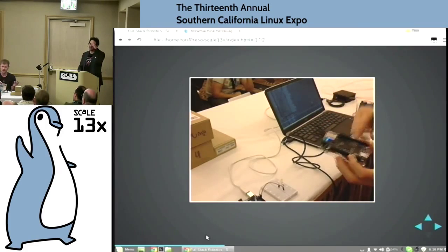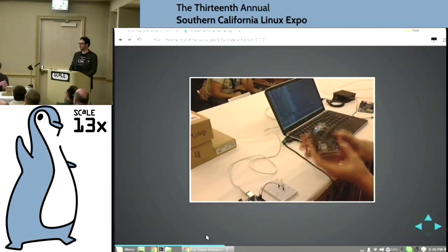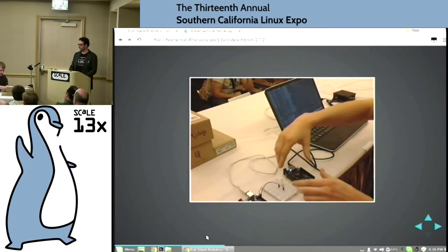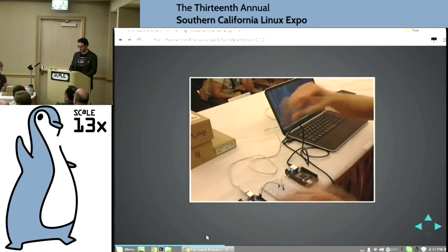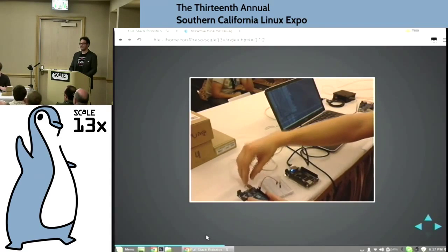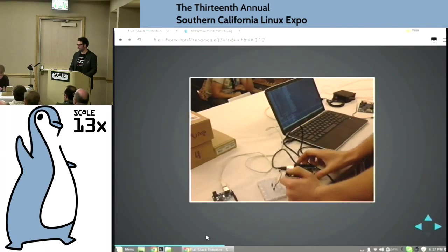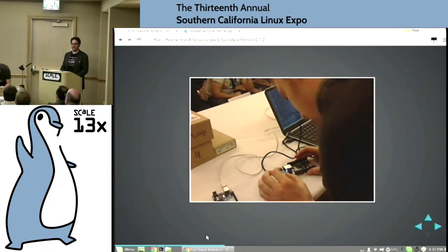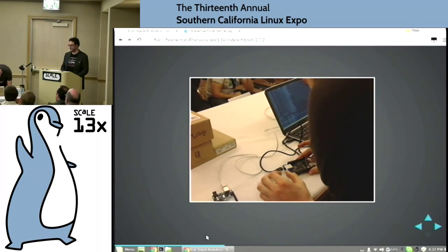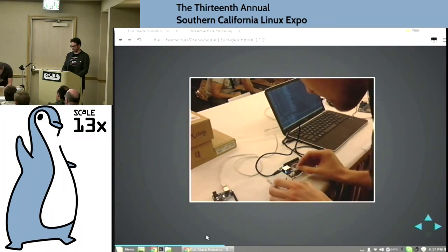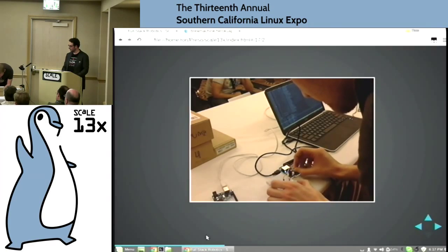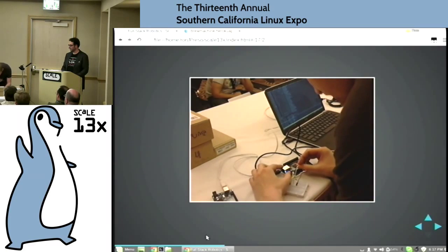So I'm actually SSH'd into this Linux computer from my laptop. Just to show you how there's no trickery here, the same exact circuit that we used for the Arduino, I'm going to plug that directly into this BeagleBone Black. This is where the labeling thing is really useful. Yeah, so this is going to go into P9 12. First we're going to put in our ground in here, and then we're going to do a little counting. So 2, 3, 4, 5, 6, 7, 8.